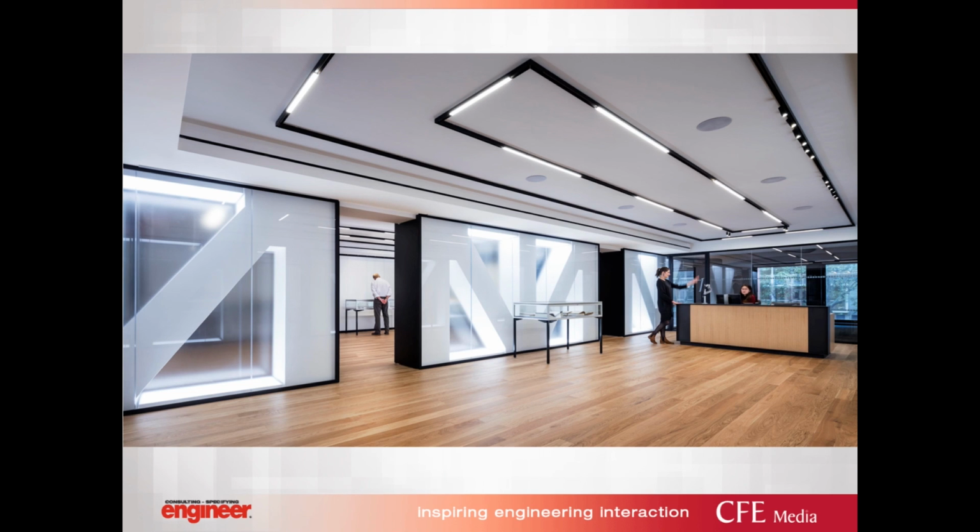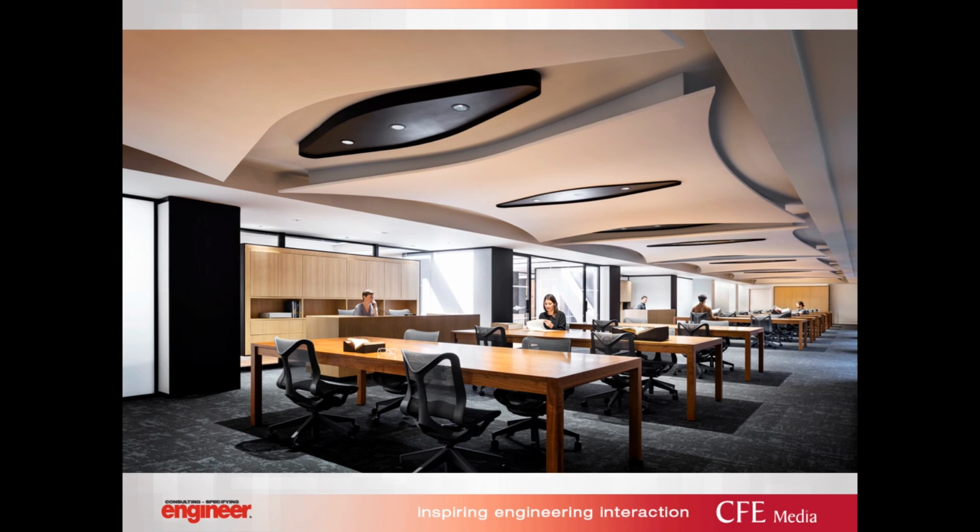This main space is a gallery space. So it had a reception desk as well as these exposed trusses that had decorative lighting embedded into them. But they also did have gallery spaces. This is an early installation, but you can see that there is a display shelf there that we would be lighting. So some of the things we were looking at were ensuring that we were using low UV sources to not tamper with any of the delicate material, as well as some of those gallery recommendations on appropriate light levels and contrast ratios in these spaces.